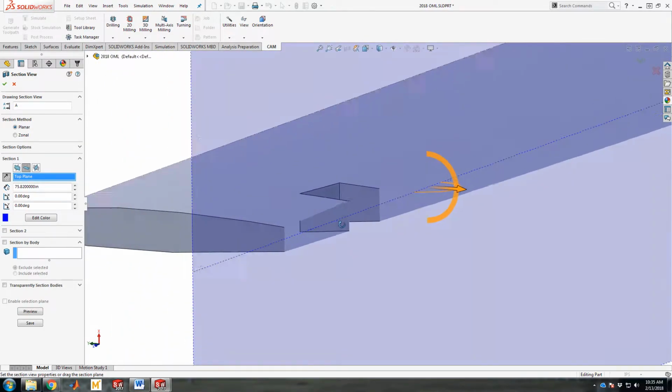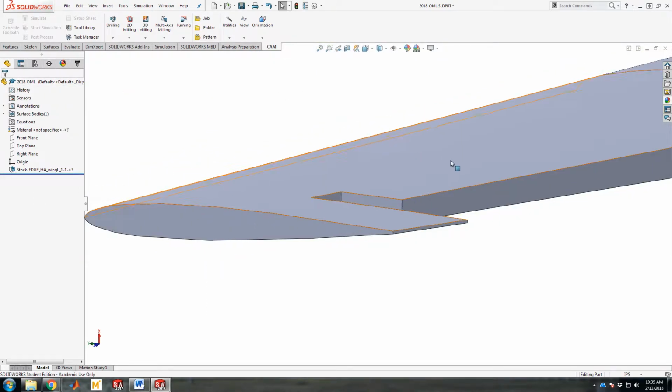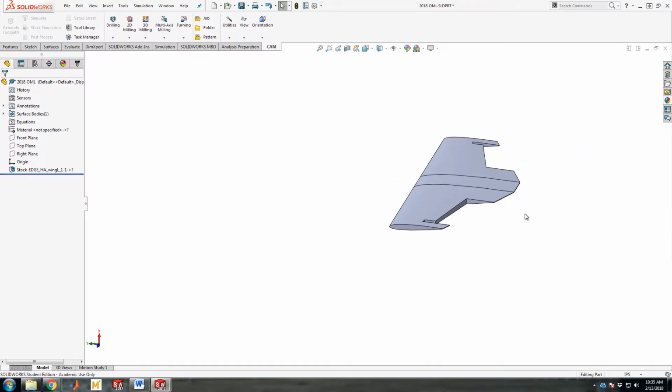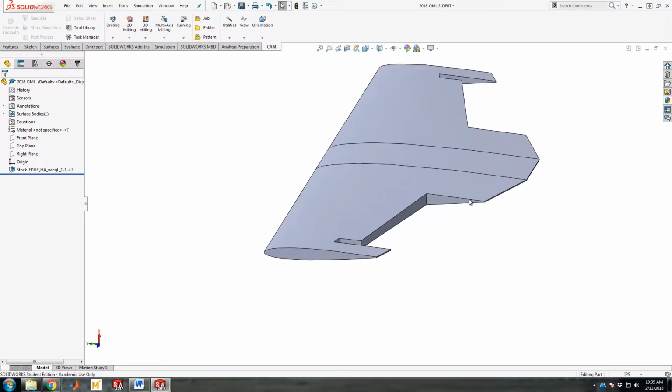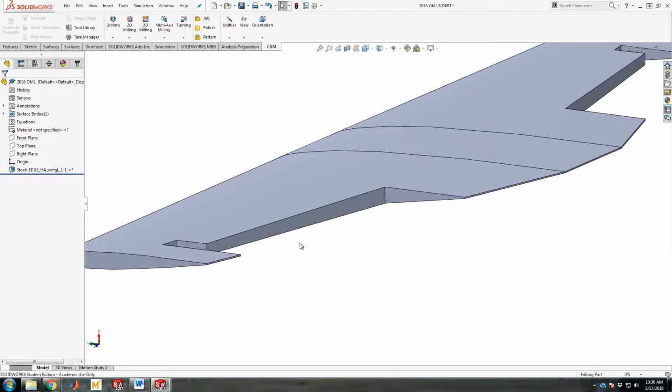It's hollow. In fact, a surfaced body is a mathematically thin shape. There's no thickness. There's no mass. It's just a surface, as you might expect. This one happens to be completely watertight. Every edge on the surface is black. If it's an open edge, meaning they're not joined, it'll be replaced by a blue line. But all the black lines mean it's closed.